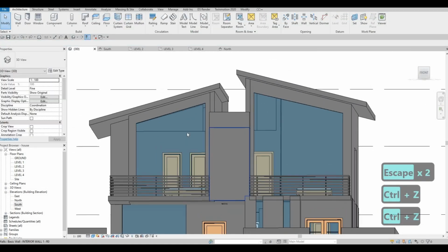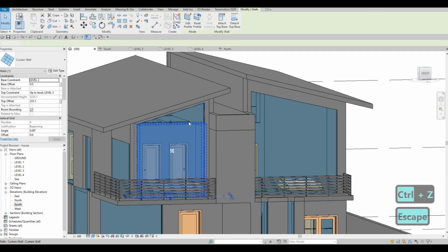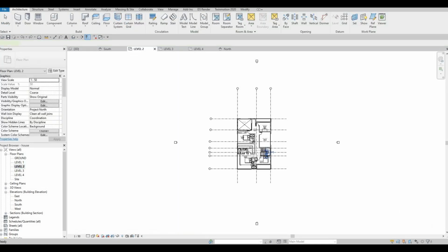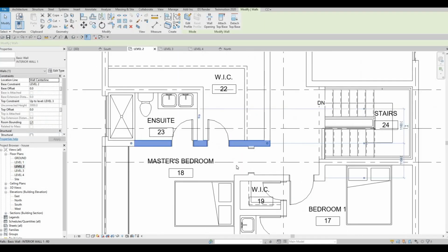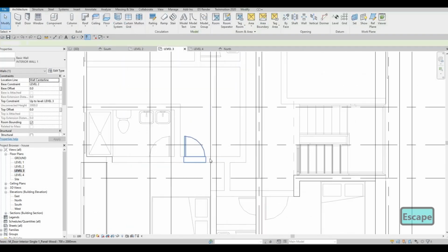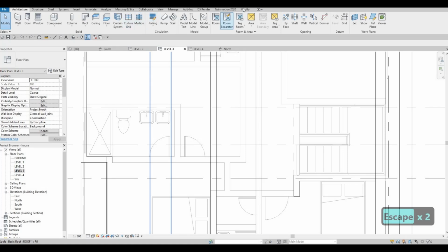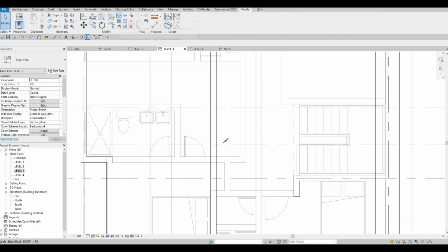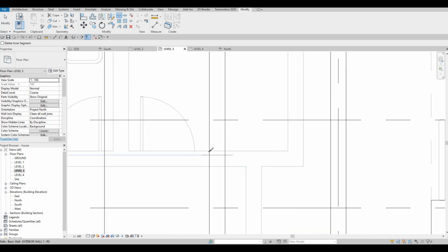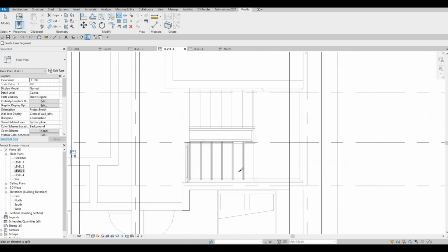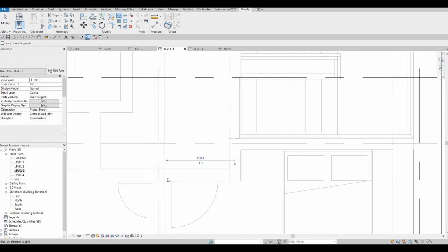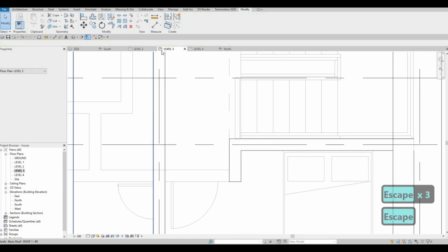Actually, it's gonna be a lot of work because we need to cut this, so let's do it right now. We'll be able to cut this now, I believe right here. So I'm gonna cut it by going to modify, and then here split element. I'm gonna split element there, and then we have one right here. So we're not gonna go all the way.